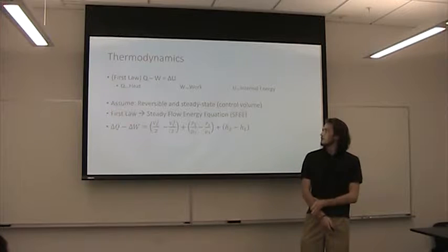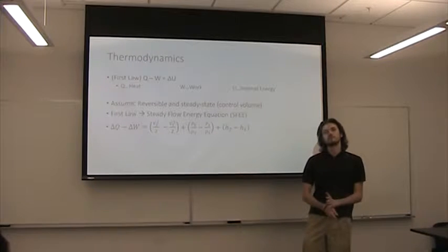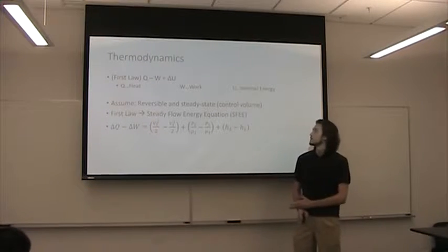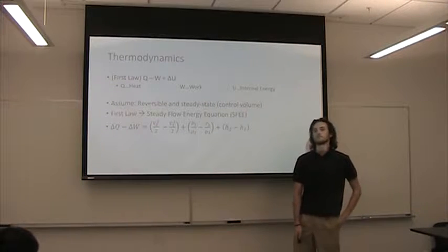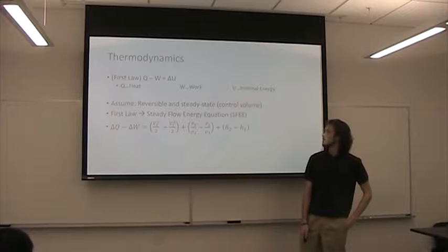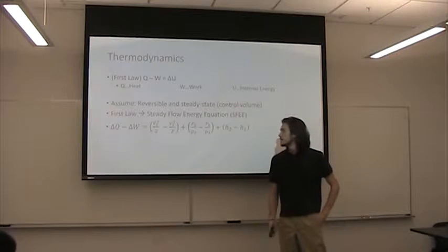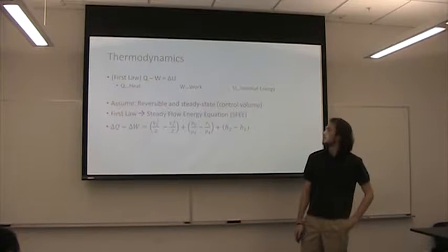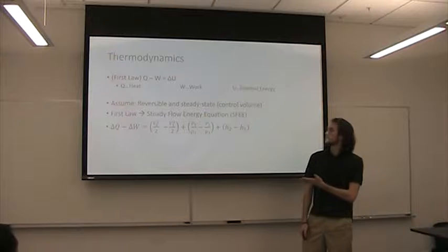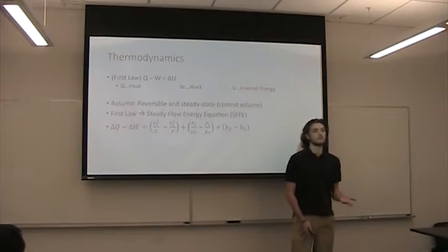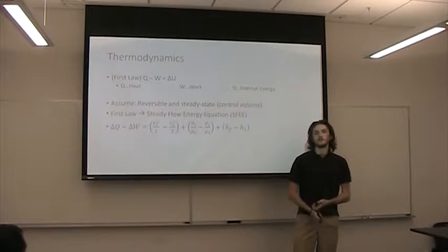Now, the thermodynamics of an internal combustion engine is using the first law and assuming that the process is reversible and steady state. That results in the steady flow energy equation. And this equation is very similar to the Euler equation used in fluids that you guys are aware of.